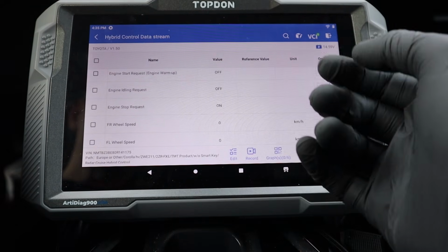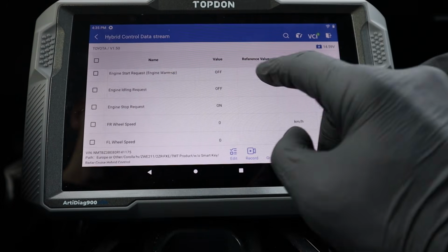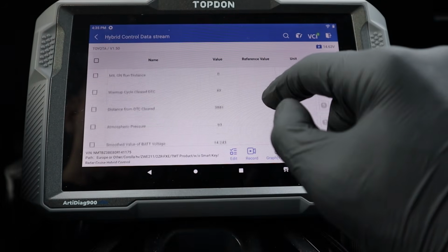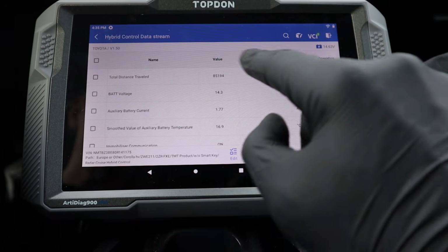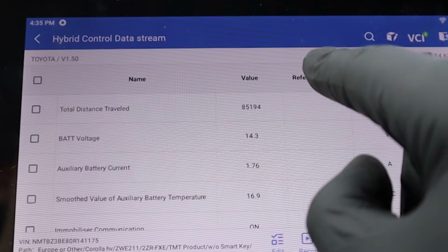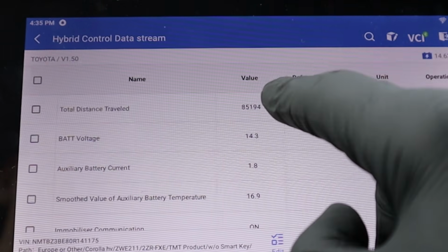The full live data is very useful when you are dealing with faults in other systems and also when it comes to a used vehicle check before buying. Because on a modern vehicle, I can find the stored mileage data in multiple control modules, and I can make sure that the mileage on the odometer is real and not fake.